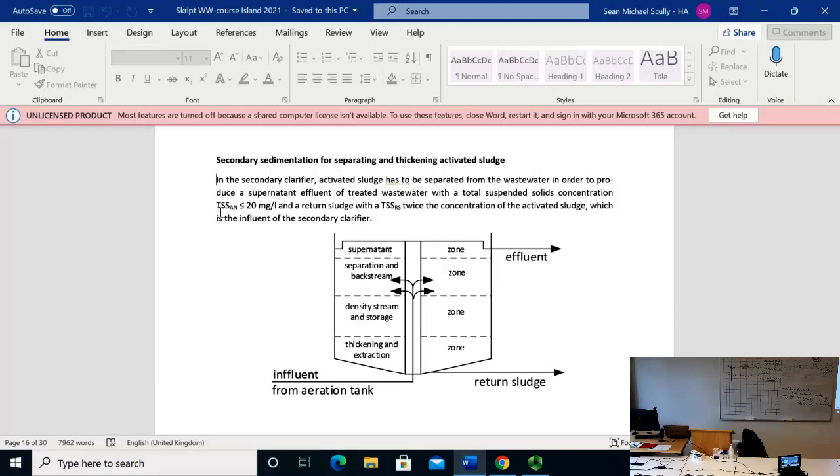The inflow normally comes from above a pipe and is separated, and you have here a standard pipe or a shaft where the water enters, and then it's evenly distributed in the circumference. The level in here, because this is open, is of course the same level which you have open here, and actually this pipe goes up higher, and you have here normally a bridge, and in this bridge, if you have those scrapers like a broom, no, like a solid broom, then we talk about the 0.7, because a broom is pushing this to the center, where you take away the return sludge.